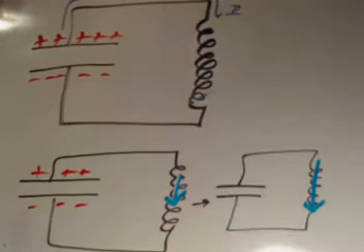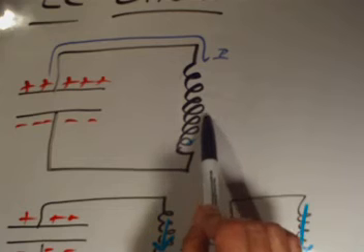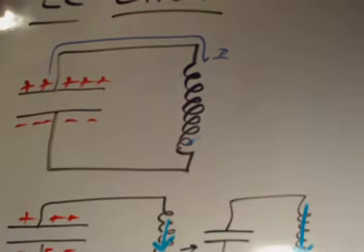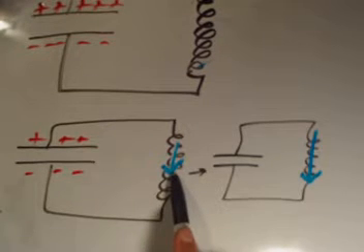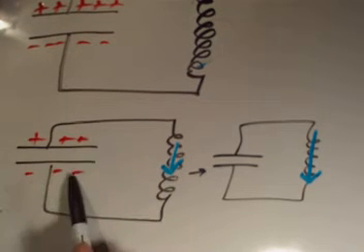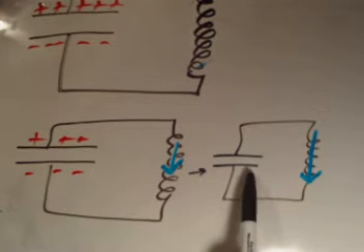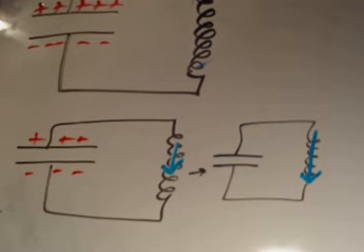I'll just keep the initial state like this here and say, well, what happens is the fully charged capacitor, the charge starts to flow off of it. The current does find this inductor sitting here, and the inductor goes through its properties. It resists current change, but eventually loses. So what starts to happen is the magnetic field inside the inductor starts to build up. This is the B field right here, at the expense of the charge on the capacitor, because of course the capacitor is giving up its energy and it's going into the inductor. And eventually the capacitor will be completely empty, and there'll be this huge magnetic field sitting in the inductor. So the question is, well, what happens now?